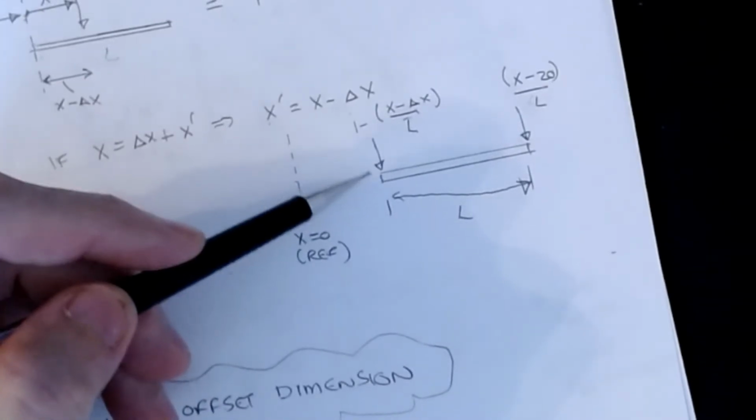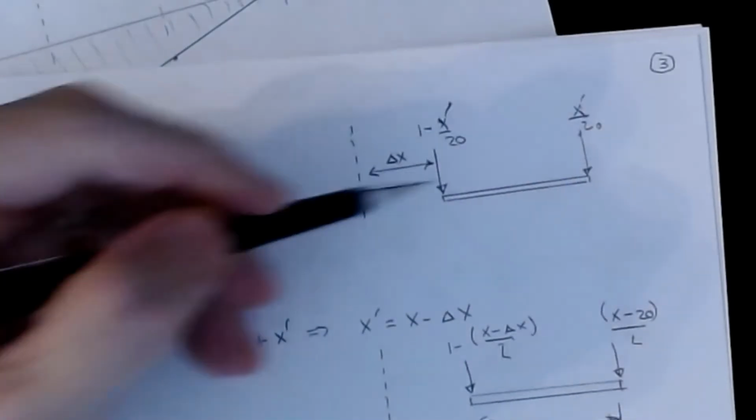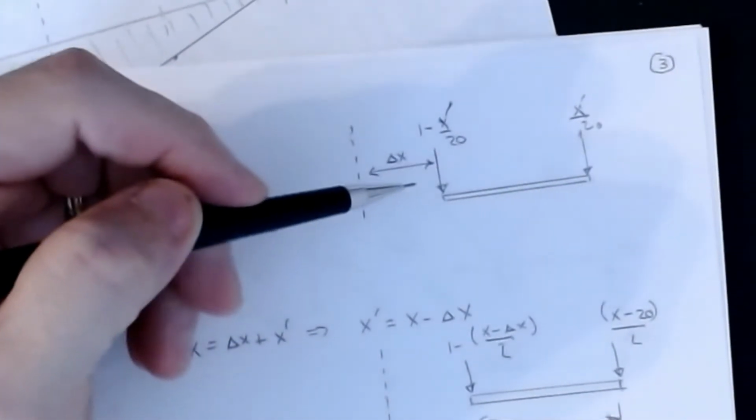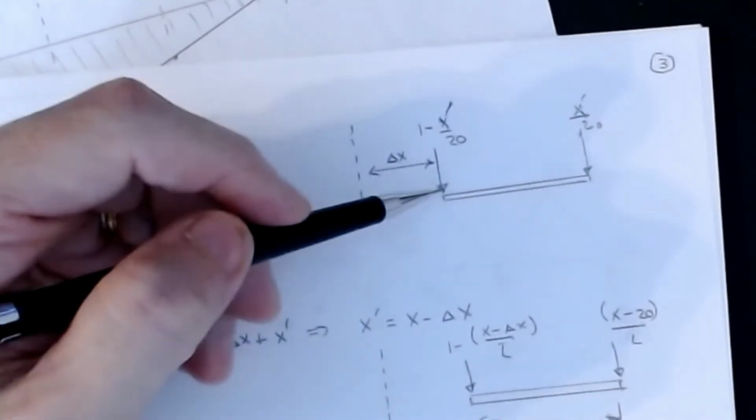And so you can kind of see that's what's happening with these pictures here, that we're basically taking that one kip load that was out here in the middle, and I'm transferring it out to the girders, if you will, and then this is what's sending the loads into the truss themselves. Okay, all right, so that's kind of what we're looking at. All right, so let's get back to it.